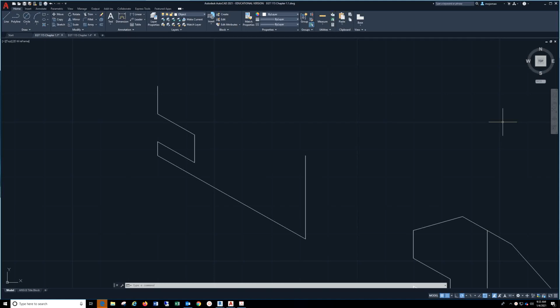Okay, video for angle spacer. Since this is going to be an isometric drawing, we're going to go down here and make sure that the isometric drafting tab is selected. And you'll see a red and green two lines at your cursor.